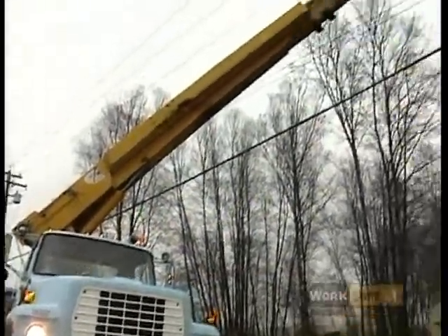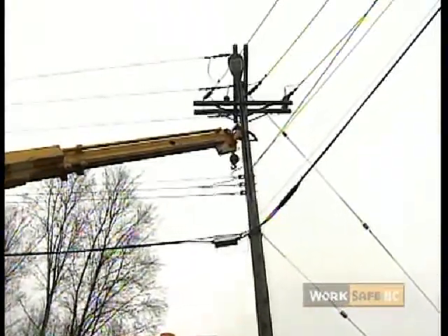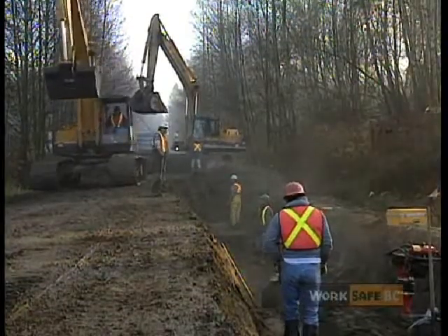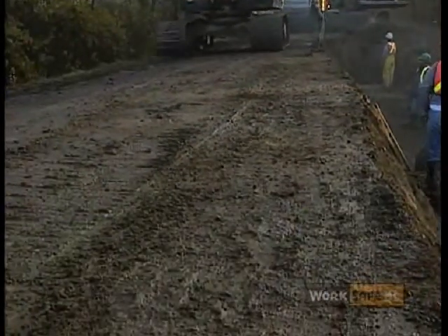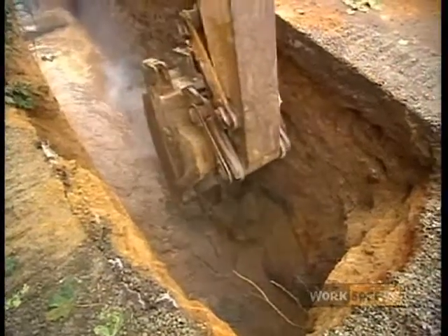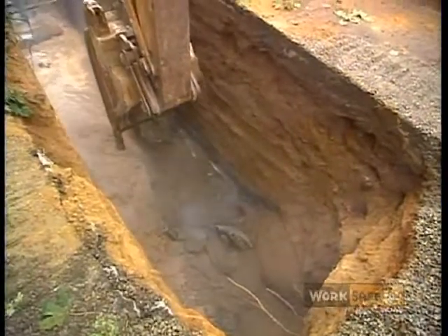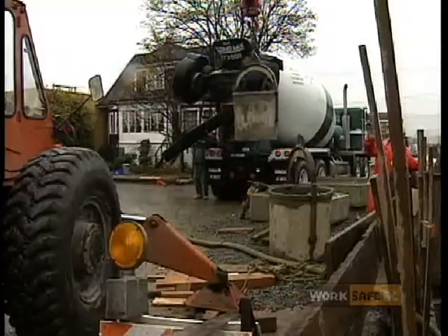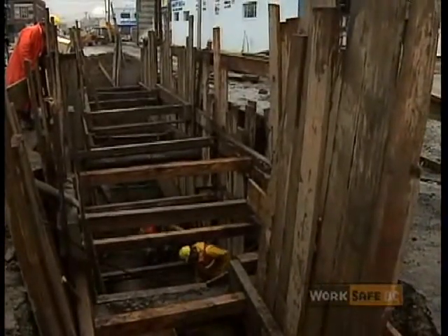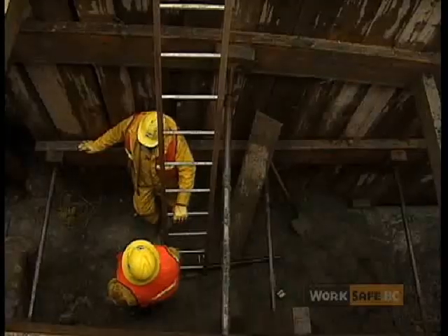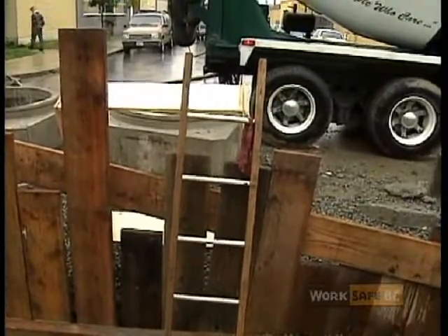Trees, utility poles, rocks, or similar objects in the vicinity must be secured or removed, and a clean, level area extending 2 feet back from the edge of an excavation must be maintained. The side of the excavation must be trimmed or scaled to remove any loose material or rocks. Safe access must be provided in the immediate area where workers are employed in trenches over 4 feet deep. Ladders must extend from the bottom of the excavation to at least 3 feet above ground.